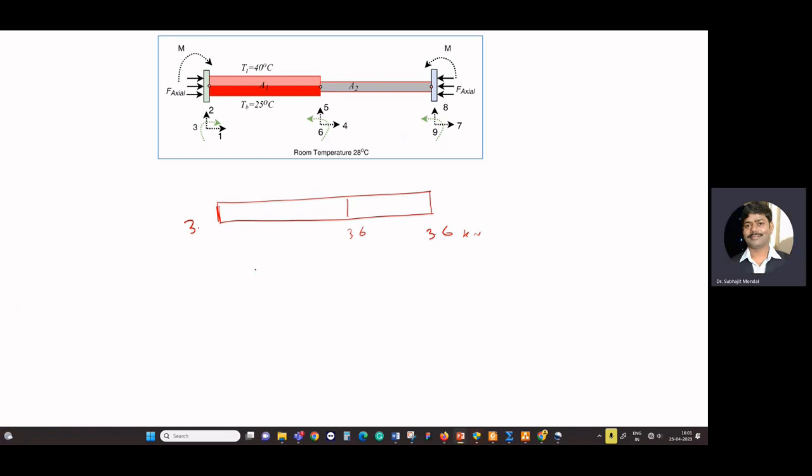Now, if you want to see how the bending moment looks, observe that at this fixed end, the moment value is 23.38, and at the other end, it will be 5.39, and if we connect these points, the variation is like this.